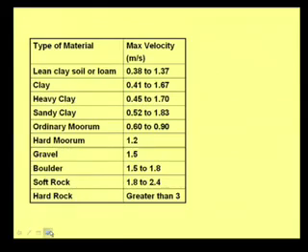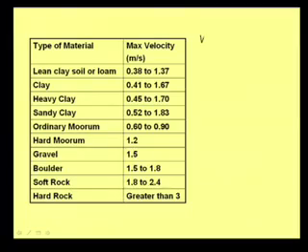Now, when we talk about maximum permissible velocity, we must have some idea of what can be our maximum permissible velocity for this particular non-alluvial formation. Once we know that, it is not a difficult task to calculate the velocity, because using the uniform flow formula, once we decide about the shape and size of the channel, we can compute the velocity by using Manning's formula, V = (1/n) R^(2/3) S^(1/2). This is very common. Once we know the slope and the dimensions of the channel, R will be known to us, and then we can compute the velocity easily.